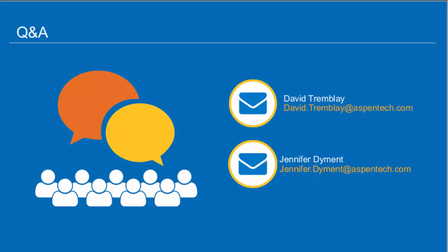Thank you. For revamp projects, can you do the economic analysis on select equipment rather than total flow sheet? In the current version, you can select which units are evaluated. We're making it a lot easier in the next release to do subsets. So, for example, to block in or select multiple blocks on the screen and just do a quick estimate for them.